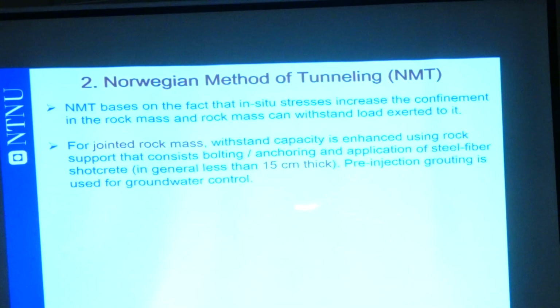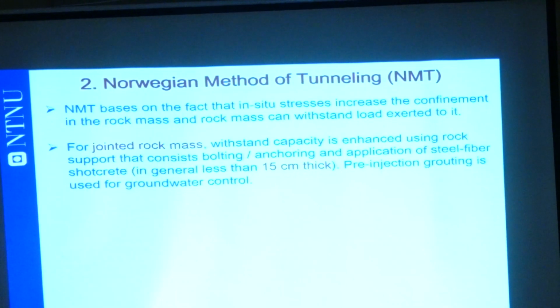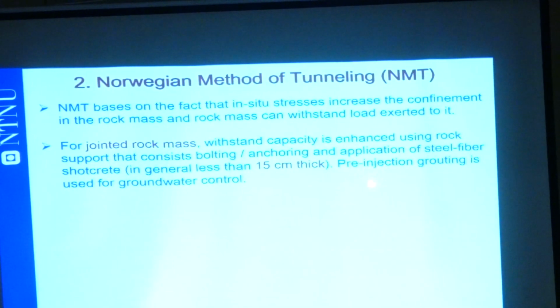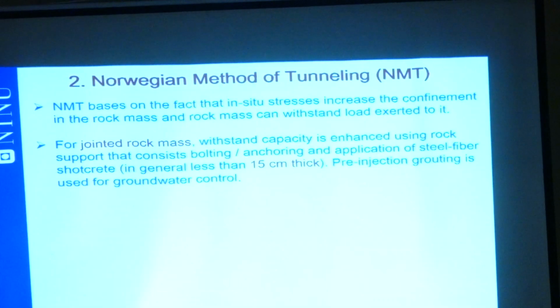And then mostly the thickness of the shotcrete is less than here. Another thing that we do to seal the joints is to apply pre-injection. We do umbrella injection so that all joints are sealed and there is less seepage or leakage. And if weakness and fault zones with swelling potential are met in water tunnels, then in those sections, in addition to shotcrete lining, we do concrete lining. Only small sections, maybe 15-20 meters.